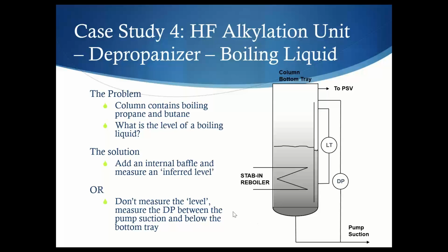Okay, so the other thing you can do is not measure the level as such, and you can look at the DP between the pump suction and the bottom tray. That's another way of doing it.